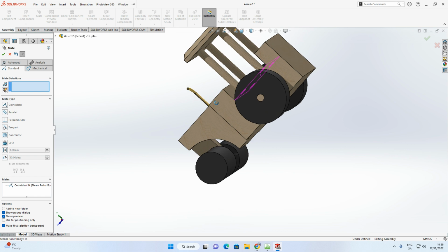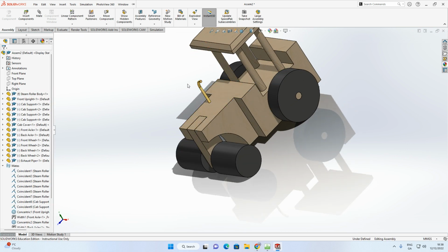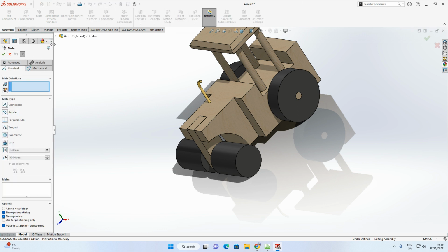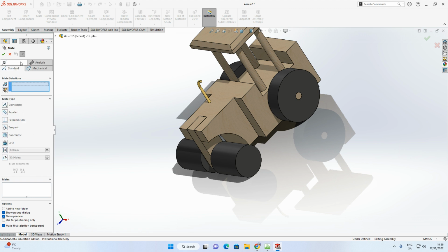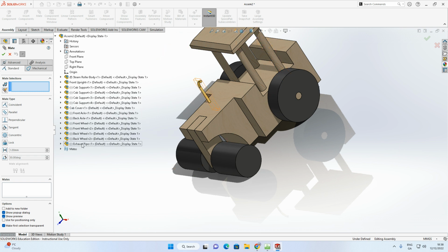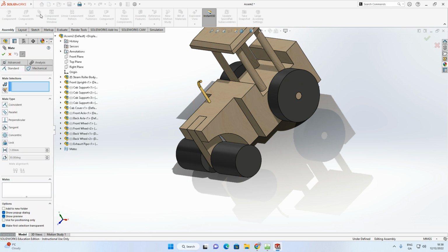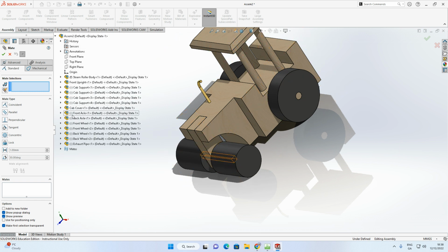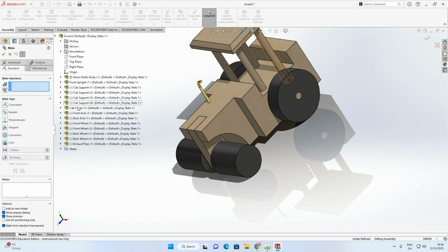But obviously, does that look correct at the moment? Not really, okay? So what we have to do is mate it with a plane. This is a bit funny now. So if I go mate, in my design tree, am I going to advanced mates here? No, I think it's just standard. In my design tree, if I select, yeah, that's it here. So I'll go back out to explain that. So mate. Now, in the mate selections, what you notice is this area has popped open here as well. This is your design tree when this area is full. So your design tree kind of pops out here.